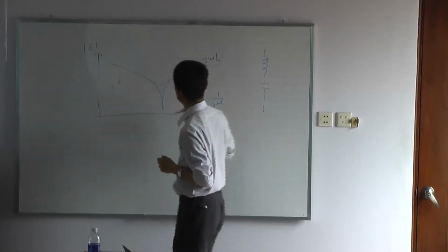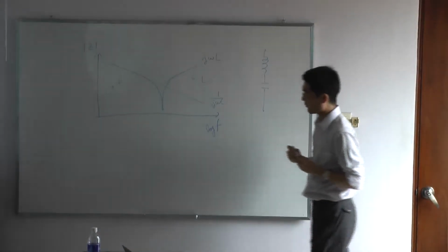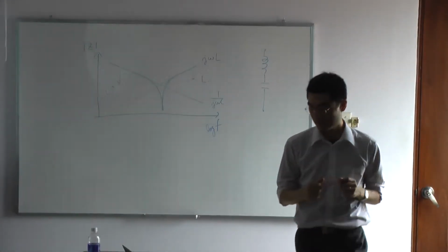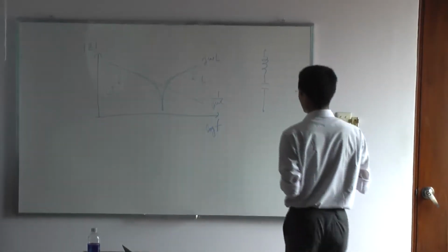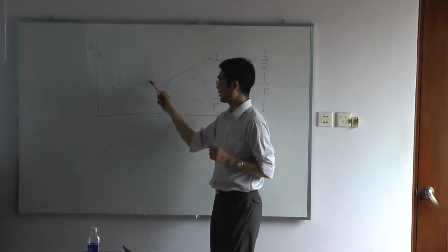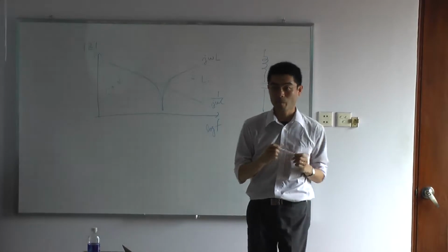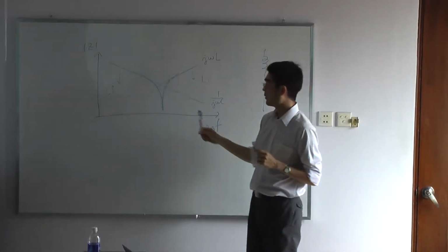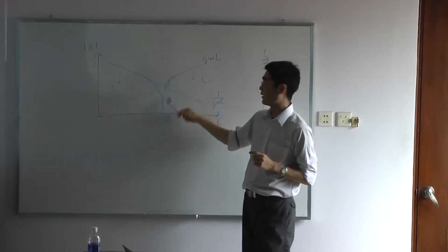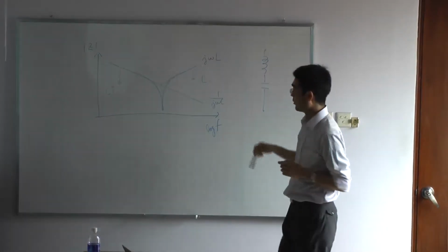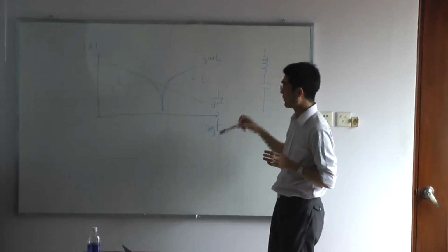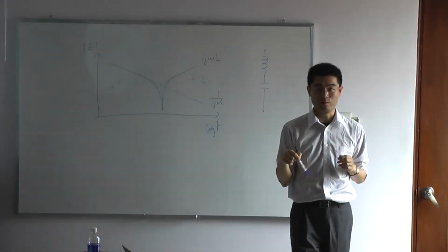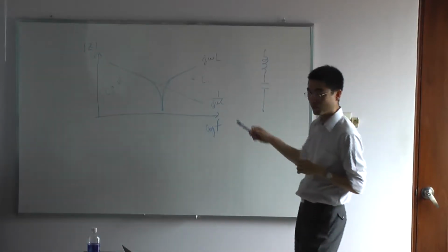Large C and small L. We want large C and small L. However, anyway, we have this kind of resonance frequency. After the resonance frequency, the impedance is getting higher, and we will have noise around this frequency. So we don't want this to happen.